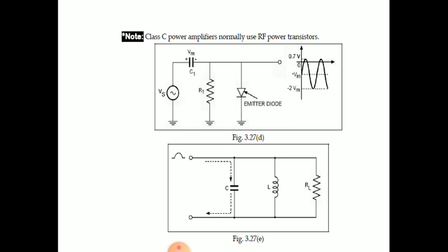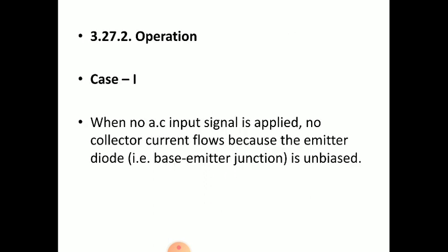Because of the periodic charging and discharging of the capacitor voltage and inductor current, the output is a smooth sinusoidal waveform, even though the input is pulses from the class C operation of the circuit, right?